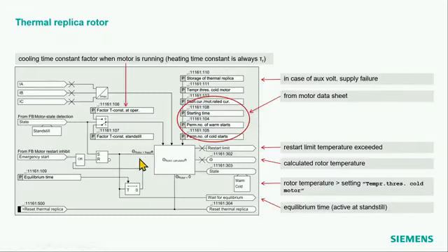And then we have another factor here. This is when the motor is at standstill, assuming that then the ventilation is not there, that the power that can go outside of the rotor into the ambience is smaller, so it takes a longer time for the cool down when the motor is at standstill. So also here we have a factor. We'll come later across that. I don't know by heart now what this factor is.